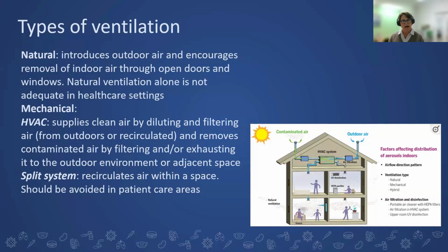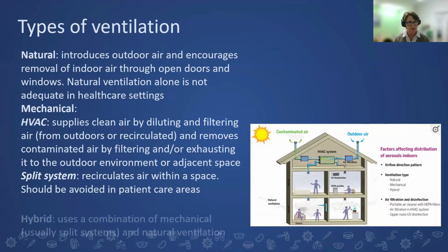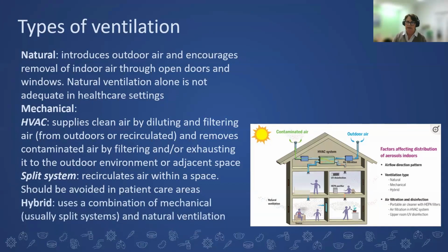Split systems tend to recirculate air within a space, and they ideally should be avoided in patient care areas, and particularly in areas where you may have patients who require airborne transmission precautions, or you're doing aerosol generating procedures. There is a hybrid ventilation system. So this is using a combination of mechanical, so quite often that split system, as well as natural ventilation.